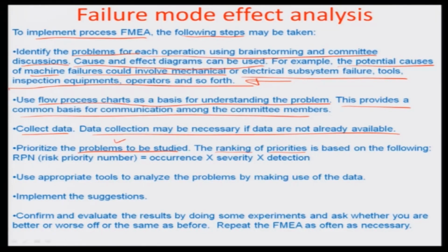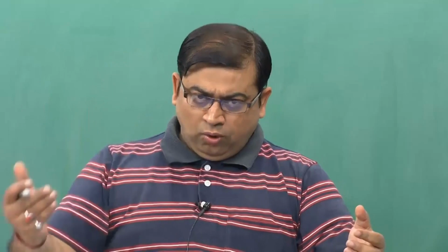And so the rankings basically would mean that you will have to rank how frequently the problem happens, how severe the problem is, and then how difficult or easy it is to detect the particular problem, and then you rank each of these categories and multiply the ranks to each other to formulate something which is now known as the risk priority number, okay. So supposing if the defect is a high frequency defect, it occurs more, then obviously the rank should be more. Similarly, if the severity of the problem is very high, the rank should be more, and vice versa. Let's say you have a scale of 0 to 10.